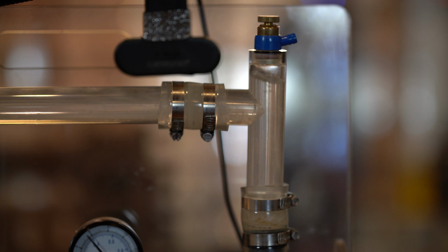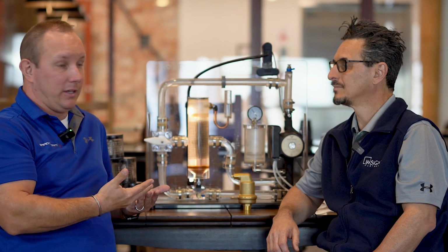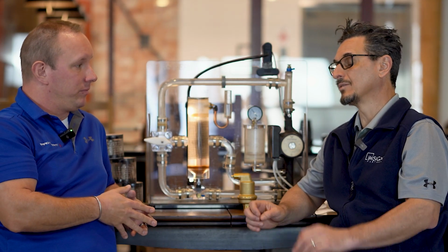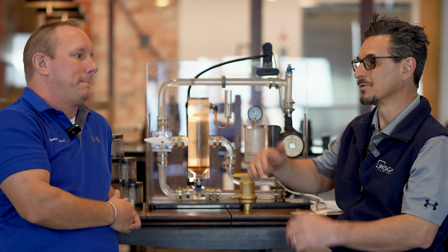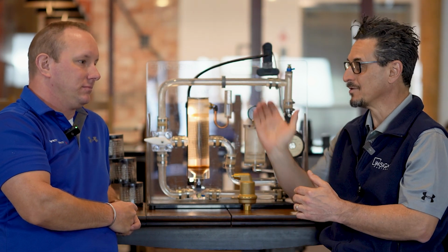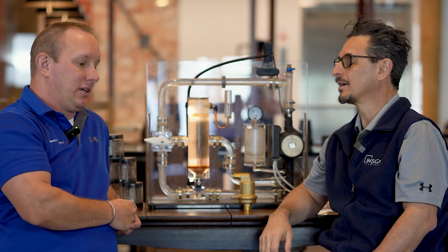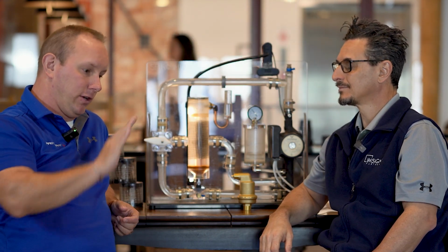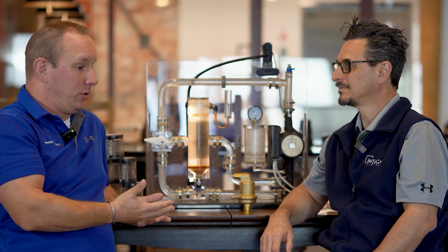So the other form of air is called entrapped air or free air. That's air that's at a high point in the system. Any point that goes up and then goes down is a high point within the system. So let me just make sure I understand. I always think of the high point as, if it's a 10-story building, the highest point is on the 10th story. So what you're saying is, on story 5, if you have an up and down scenario, you can still get entrapped air. Correct. Okay. If you had a wave of pipes, so to speak, each top crest of that wave would be a high point.